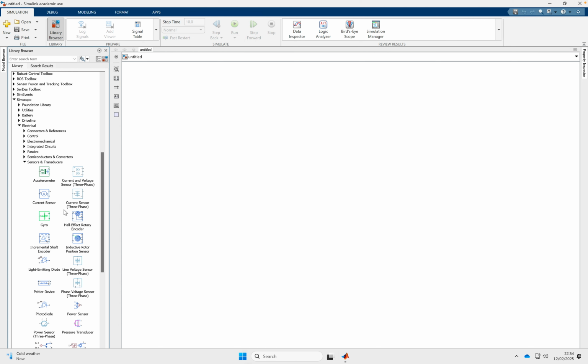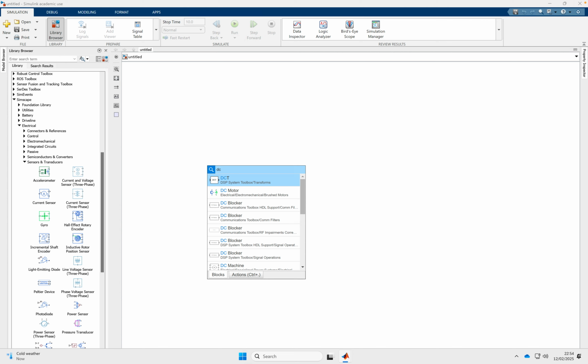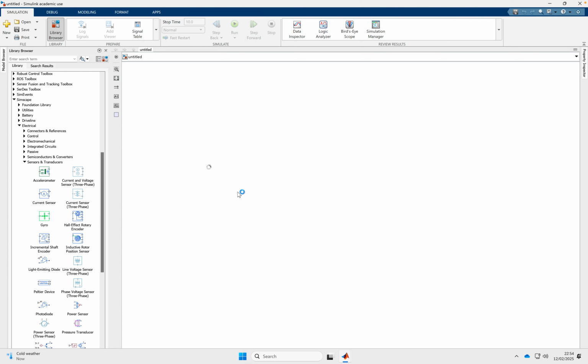So what I'm going to do for us to finish this video quite early, I'm just going to type here on the environment. So the first thing we need is a voltage source, a DC voltage source. So we click here on the environment, we type DC voltage. So we need a DC voltage source, right? Which is direct current. So we click our DC voltage source and there it appears.